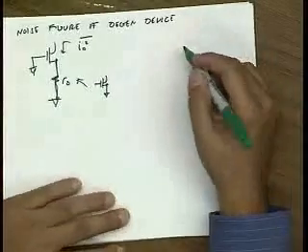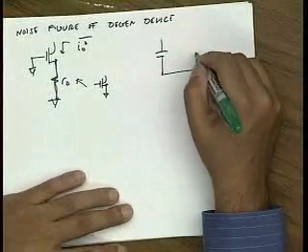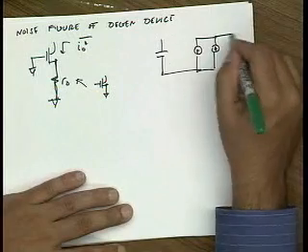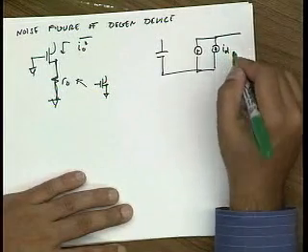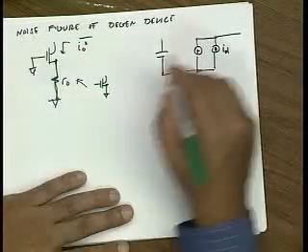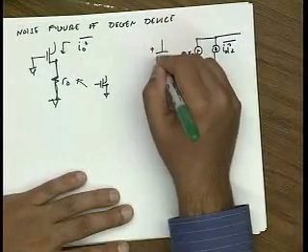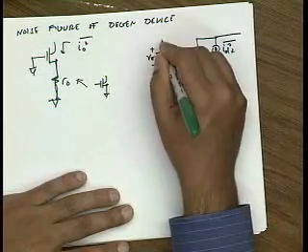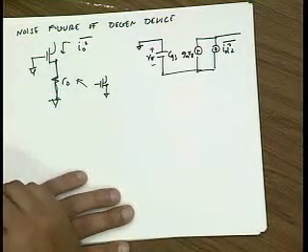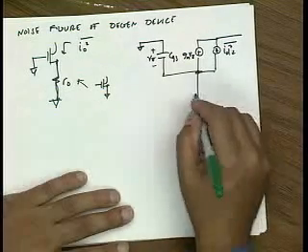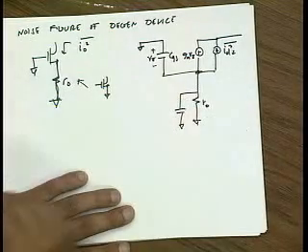Okay, so let me draw the equivalent circuit here. We can very quickly analyze this problem because we've already seen it. This is the drain noise of the second device. This is I drain 2. This is GM V pi. This is V pi again. CGS. The gate is grounded, and I have a very large resistor here, RO. And in reality, I also have some cap.